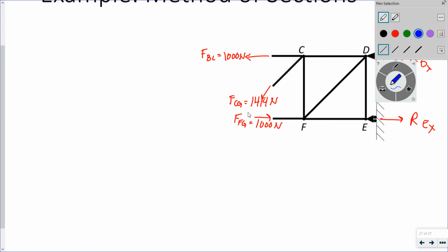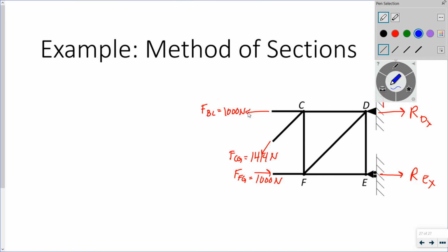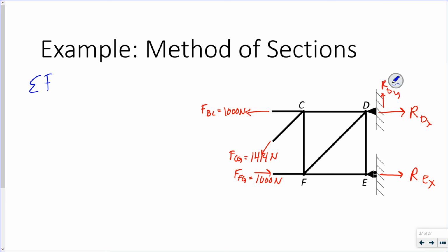So let's start with the sum of the forces in the y direction. The only y direction forces that I have are the vertical components of the member force FCG, and then this reaction.